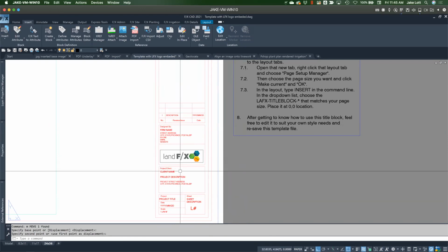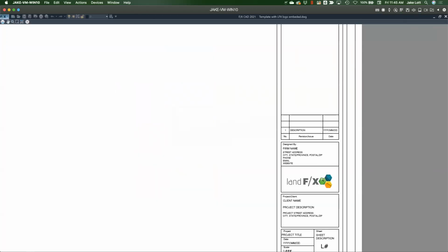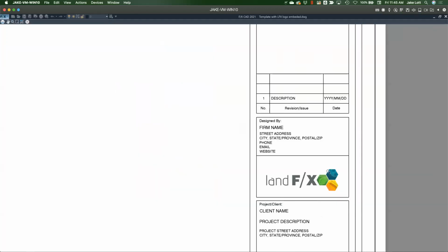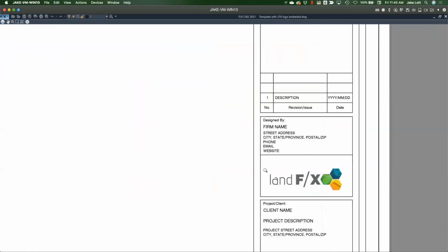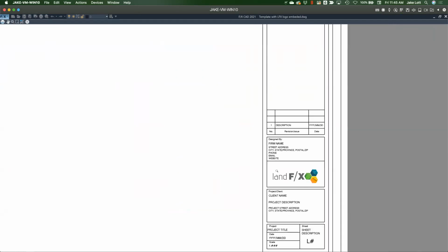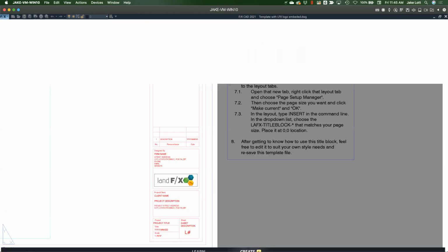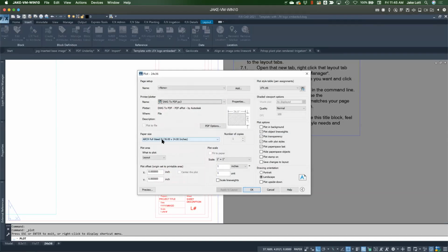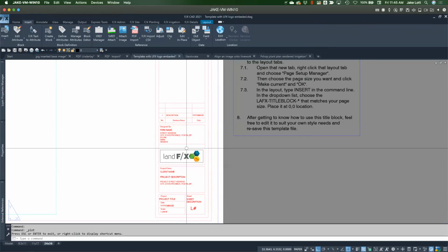So once it's here and you go to plot it or whatnot, you're going to see that it's going to read in just like that. We have our setting for that OLE frame system variable to 2, which means we can see that frame, but it doesn't plot. So that's my preferred way, so that you don't have little borders on everything. So that's that fun little embedding thing.